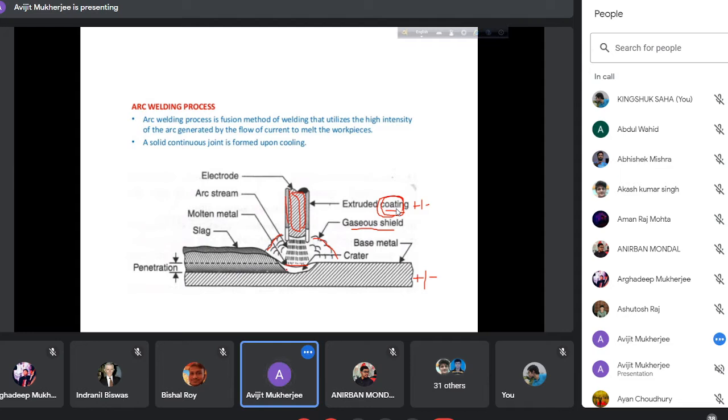You are familiar with the term heat treatment. Due to this quenching, particularly when the metal is enriched with carbon, martensite will be formed and the metal will immediately crack. A very brittle structure is formed due to quenching, and crack formation occurs.